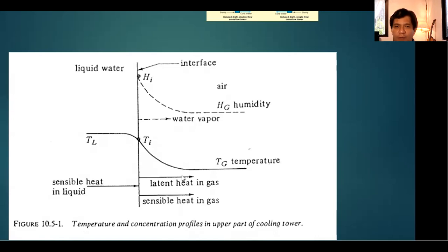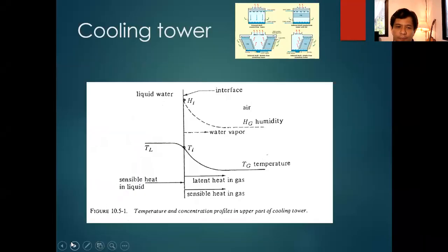As for the sensible heat, what is that? Euler's law, or Newton's law? It's just Newton's law. Okay? Question? Do you have any questions? The essence of this slide is that there are two reasons why the water cools when you mix it with air. First, the air is colder, so the water will cool when you mix them. The second reason is that evaporation occurs, because the air is not saturated, so some portion of the liquid water will evaporate. Question? Let's proceed.